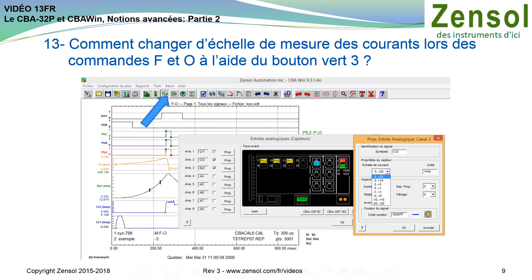If you make a current measurement of 1A when the chosen scale is 20A, you won't necessarily get the best signal. So you need to think about changing scale to get the best possible accuracy. Older circuit breakers draw a very high coil current, whereas new circuit breakers draw a very low current, often less than 1A. The CBA-32P control circuit has current protection via the control cable, which incorporates 25A fuses that are easily accessible for replacement.